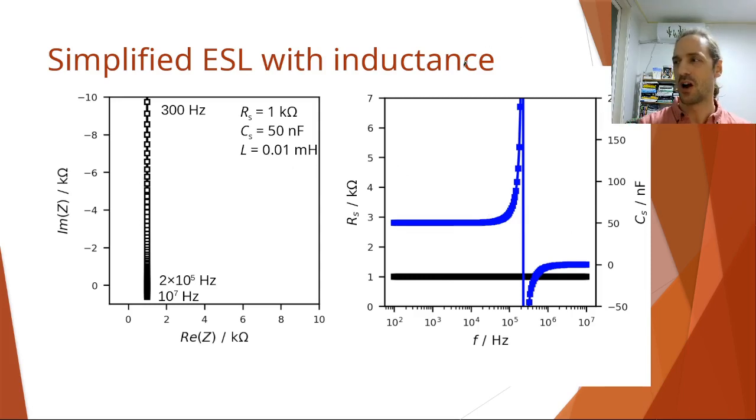So in the start, we talked about how the inductance is only affecting our measurement at high frequencies. So you can see that if we have an inductor, in this case I didn't put the minus sign here, but rather here. But anyways, we can see that at high frequencies, because the inductive reactance is a positive value, the high frequencies will start from here, and as the frequency is going down, we'll go back to the negative regime.